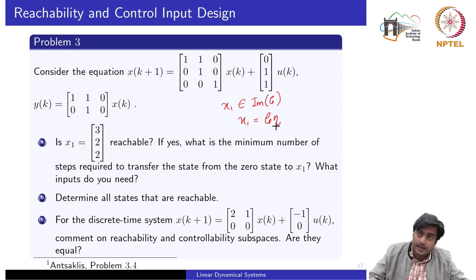If we put in this x1, which is given here, and we have the controllability matrix with us, and we are able to find that eta vector, then this state is reachable. One straightforward way to compute this eta would be to compute this directly, but we cannot take the inverse of the controllability matrix because it is rank deficient. It is a singular matrix.